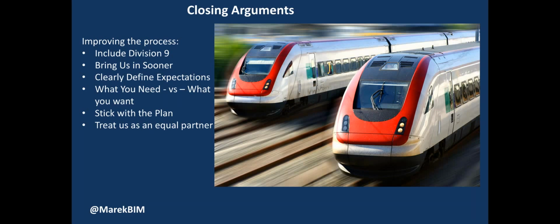Next, clearly define your expectations. We get a lot of projects that we're on that they're not sure what our role is. Our scope is pretty unclear. I got a BIM execution plan the other day that the level of development was called medium. I don't know that they'd heard of LOD 100 through 500. They just said LOD medium. We weren't sure quite what that meant. So clearly define your expectations, what we can do for you, how we can help the process. That'll help everybody in the long run.